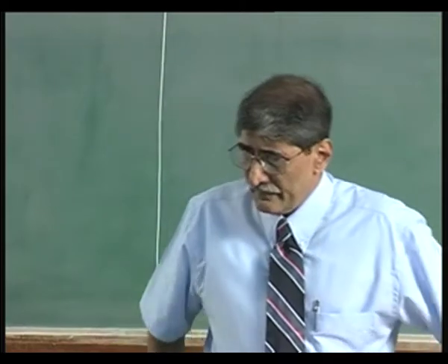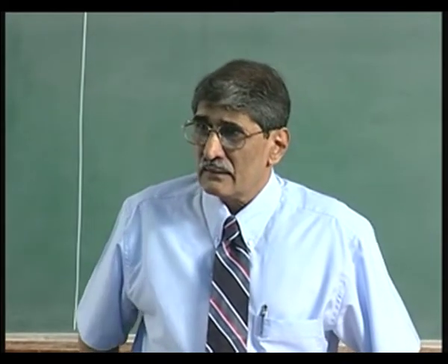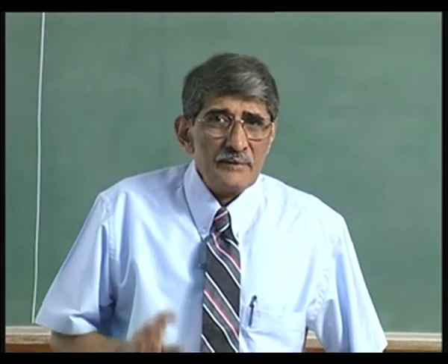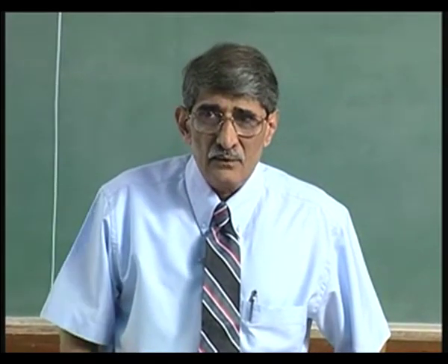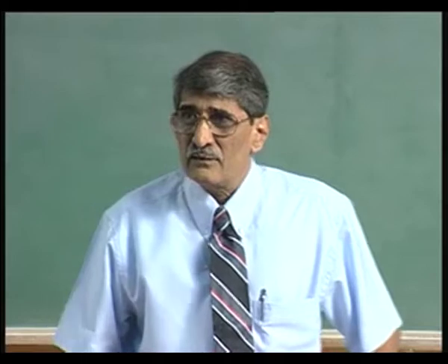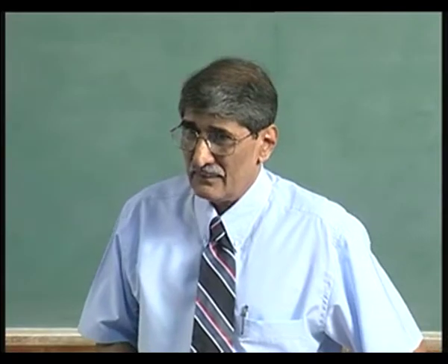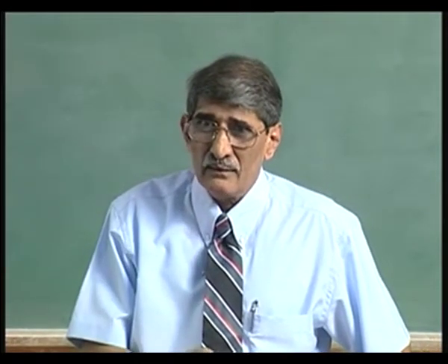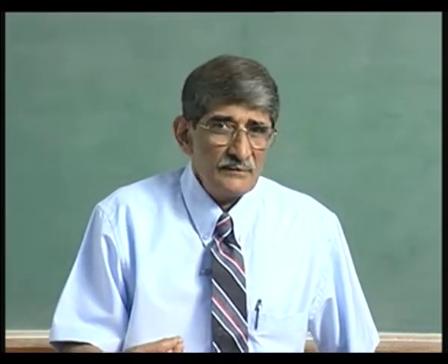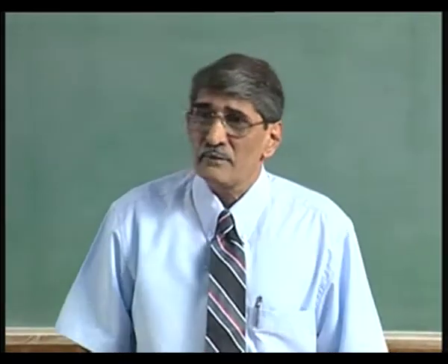Okay, last time we went through the details and discussed the crystal structure of gallium arsenide. In fact, what we discussed for gallium arsenide holds good also for indium phosphide. That also has got zinc blende structure. Most of these 3,5 compounds have got zinc blende structure. So, wherever gallium was supposed to be sitting, you will have indium. Wherever arsenic was supposed to be sitting, you have phosphorus. So, in general, 3 and 5 elements are sitting there to form the zinc blende structure.